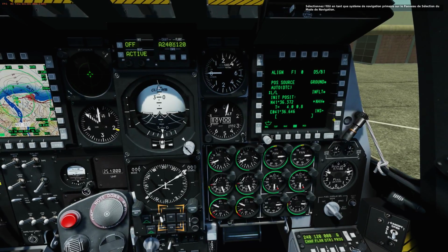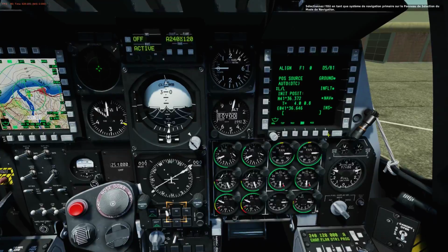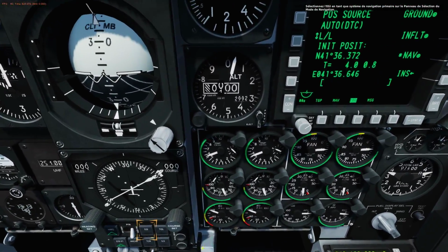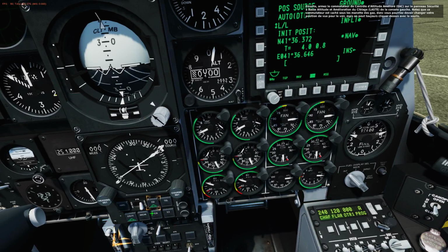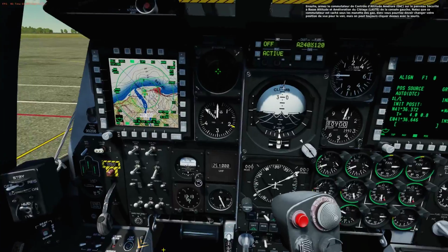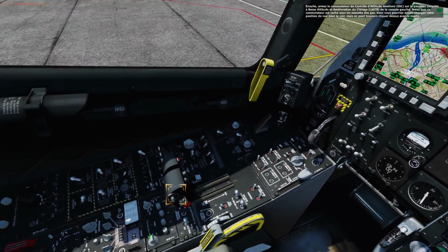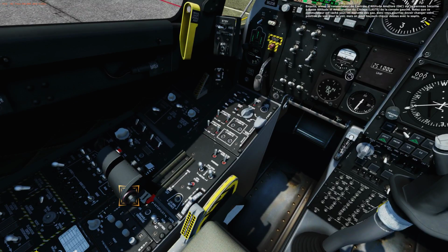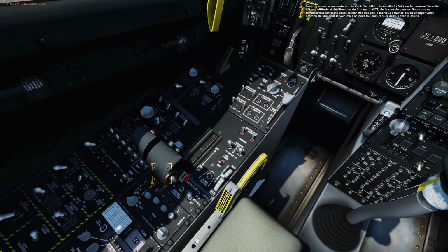Select the EGI as the primary navigation system on the Navigation Mode Select panel. Next, arm the Enhanced Attitude Control, EAC, switch on the Low Altitude Safety and Targeting Enhancement, LASTE, panel on the left console. Note this switch is hidden under the throttle, so you may have to shift your view position to see it, but it is still clickable with the mouse.